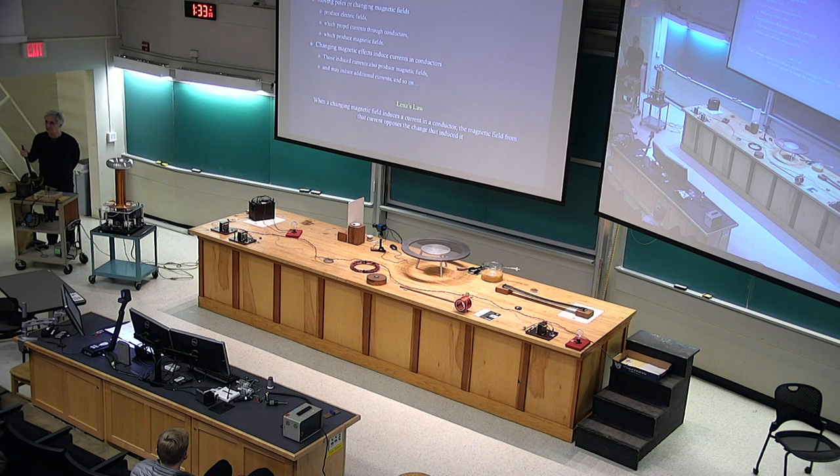But this is still consuming electric power. Why? Because it still has to keep the current flowing through the coil, and the coil is made of conventional, ordinary metal. Copper, it's good copper, but it's not perfect. And so keeping that current flowing through wires takes energy. You've got to have a voltage drop in the wire to keep the charges moving forward by way of an electric field, and that's wasting energy, and the coils are going to get warm. I don't know if they're warm now, and I don't really want to touch them for fear that they're not perfectly insulated and I will become a light bulb.